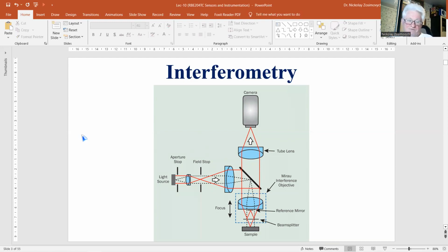In an interferometric sensor, such a phase difference occurs due to a path length difference between the two light beams, one of which usually follows a reference path, and the other a path of which the length is modulated by a movable part of the construction.